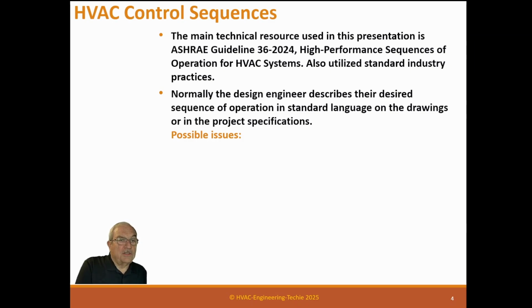Normally, the design engineer describes their desired sequence of operation in standard language on the drawings or in the project specifications. However, there are problems with this that I have encountered in my career: new innovative design sequences never used before. So a smart young engineer will come up with a sequence that they think will really be slick and really make this system efficient and work well. But it's so complicated, or it's something no one's ever seen before, it's a problem, because without having prior experience or testing a system, it gets very difficult because the amount of testing required is extensive.